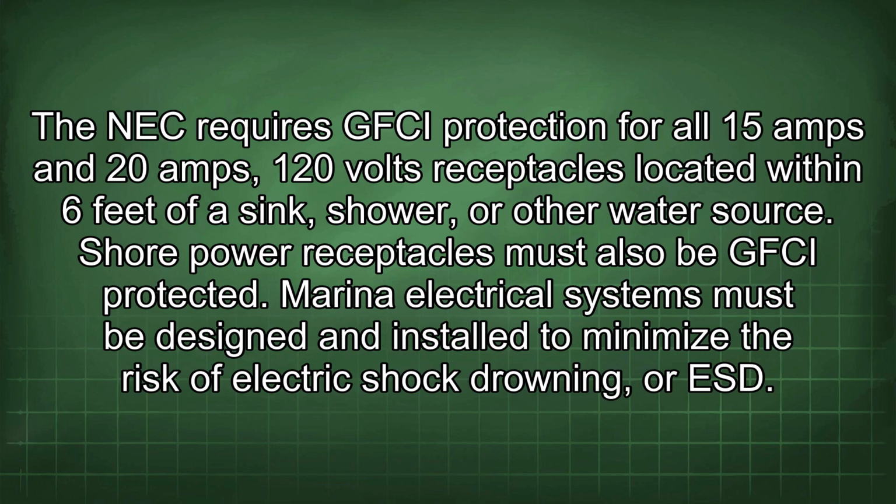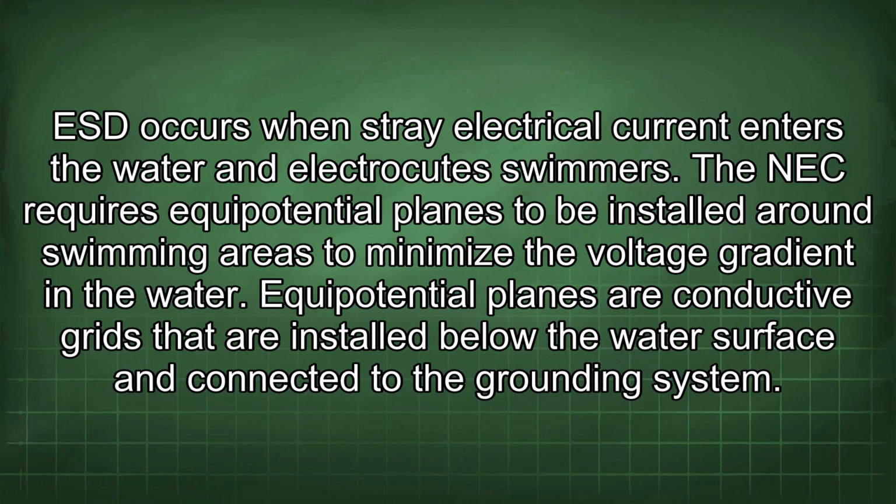Marina electrical systems must be designed and installed to minimize the risk of electric shock drowning, or ESD. ESD occurs when stray electrical current enters the water and electrocutes swimmers. The NEC requires equipotential planes to be installed around swimming areas to minimize the voltage gradient in the water. Equipotential planes are conductive grids that are installed below the water surface and connected to the grounding system.